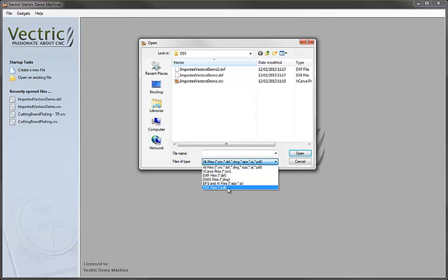The final one we support is the PDF file, but it's very important to note that this file format is a printing file format that supports lots of aspects to do with printing, which our software's not interested in. It also potentially has bitmap files in it, and at the moment the software will not import any bitmap files. So if you find a PDF file which has both vector and bitmap data in it, we will only extract the vector data from that file. So it's important to note that.